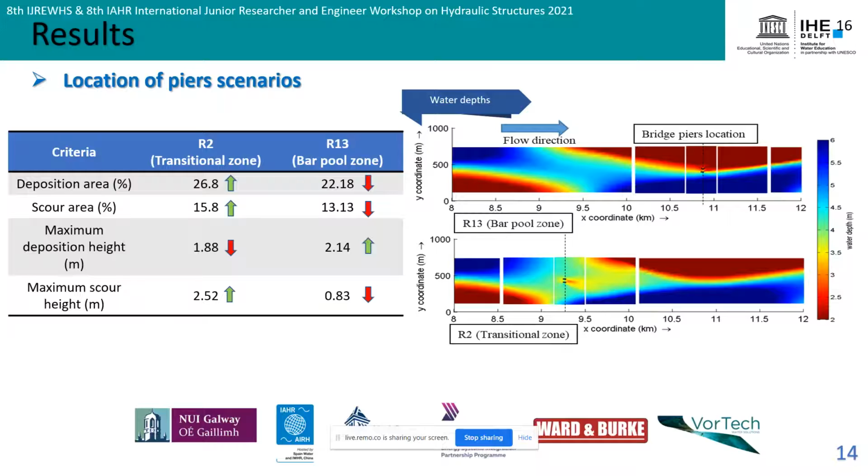we install the bridge pier in a flow dominated area generated by the presence of the hybrid bar on the other side of the cross section, while here the bridge piers are installed in a transitional area which is not significantly affected by an existing bar, so the bridge piers could show their effect in a symmetric way by forming this central bar, as we can see here.